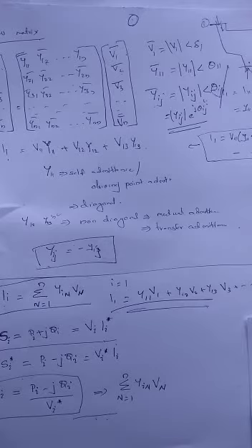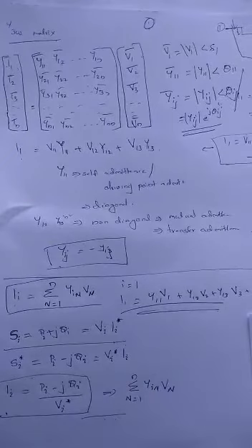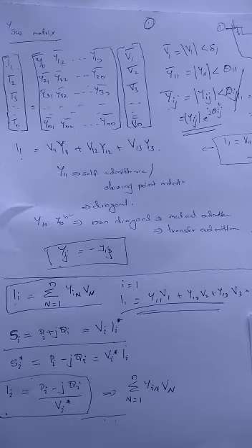For load flow analysis we employ the admittance matrix because of its many advantages. The admittance matrix is very easy to find, and we can represent all the elements using it. Usually the admittance matrix is a symmetrical matrix. It is also a sparse matrix, which helps the computations.